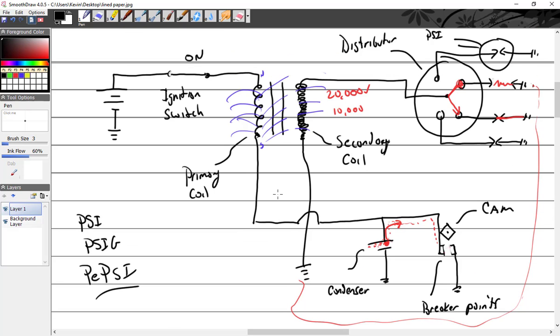Okay, so number one, this distributor finger, this finger that goes around, this one right here, that one goes, and it's tied to the cam. So really, these two things are usually physically right on top of each other. And they're driven off of a camshaft, not a crankshaft. The crankshaft is the thing that goes around, makes the pistons go up and down.